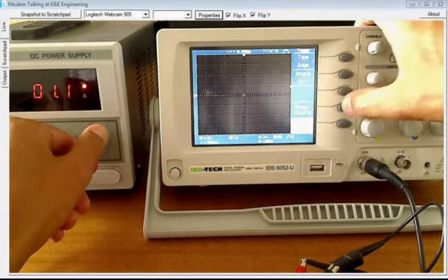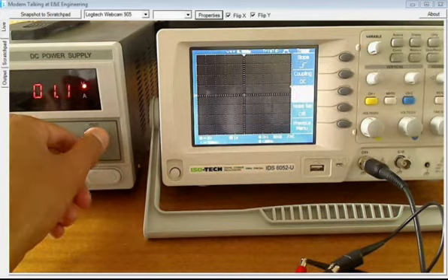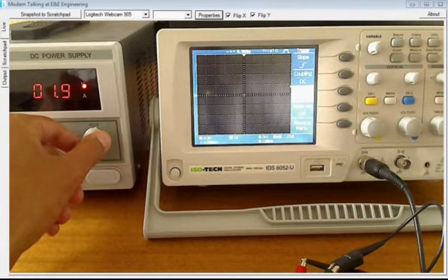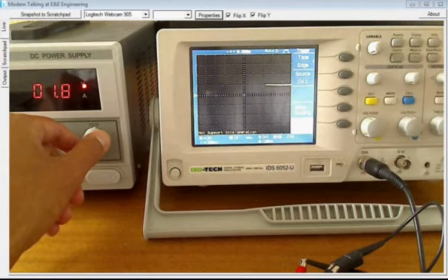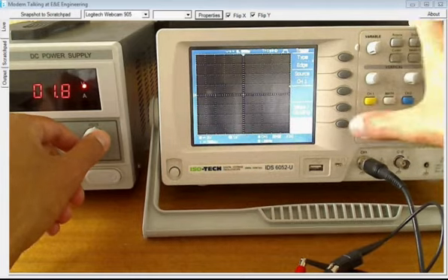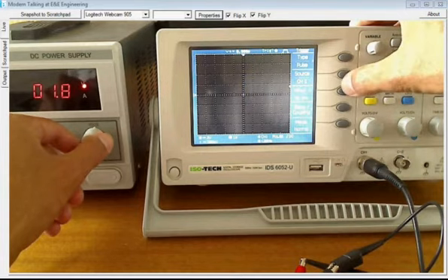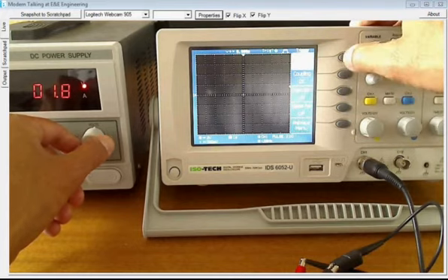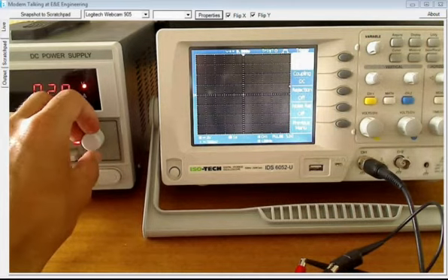Actually, it's triggering on a rising slope. You can see it's waiting for a rising slope. So if I go above 1.3, I'm expecting it to trigger. It doesn't. I don't know why. Just select trigger menu auto and just find where I am. And then normal. Yeah. And then edge type, pulse, source, slope. And I'm going to trigger on a falling edge.